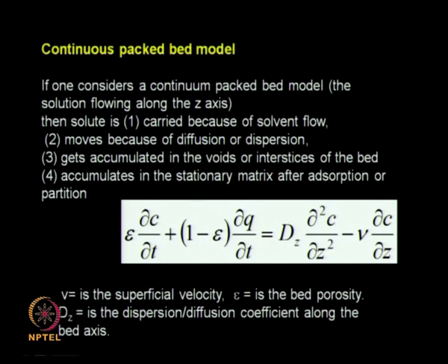The solute is moving from left to right along the z axis, and the solute is carried because of solvent flow, because of diffusion along the axis of the tubular bed or dispersion, solute gets accumulated in the voids or interstices of the bed, and the solute is also present adsorbed onto the stationary matrix.